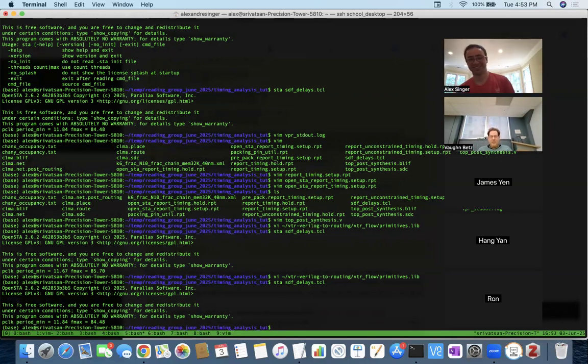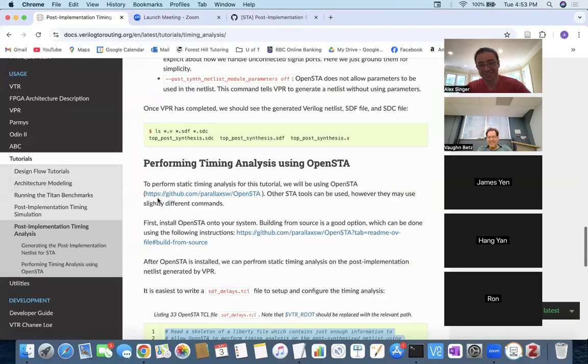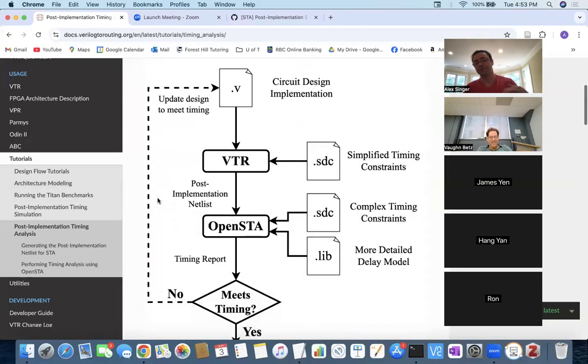A lot of this, you're right. Carrying a more complicated delay model slows down your timing analyzer, but we could probably carry a moderately more complicated delay model without too much impact, because you spend a bunch of time traversing the graph. So if you do a little more work at every node, it's not that bad for a while. But they simply kind of go right out of code. And the gains you might find in VTR might be small. For all that extra work, you might get a better critical path delay of a few percent or so. It might not be that big, so it may not be worth it.